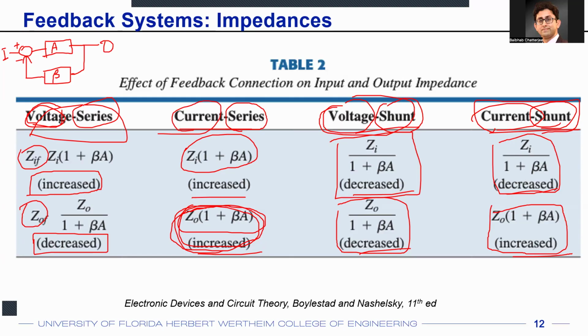Yes. That's a good question. When you talk about a type of amplifier, for example, voltage amplifier or current amplifier, a current amplifier means your input is a current. And of course, as we're talking about amplifiers, we're always talking about AC amplifiers, right? So you'll have an oscillating sine wave maybe at the input. If your input quantity is current, then your current looks like a sine wave, which may mean your voltage also looks like a sine wave if your impedance is linear. If your impedance is constant, then your current and voltage look the same.